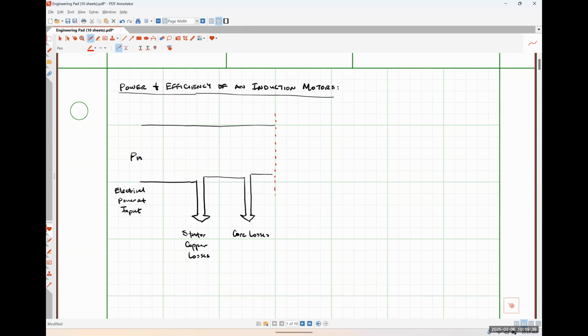If we're looking at this as an electromechanical energy conversion system, we've got our input energy into the stator and the losses associated with the stator. Now we're getting into the field energy portion of things. This line essentially represents what's happening at our air gap. I'm going to call this the air gap power, and give it the symbol PAG. This is the amount of power that crosses the air gap and is being converted into the mechanical power that's spinning the rotor, essentially.